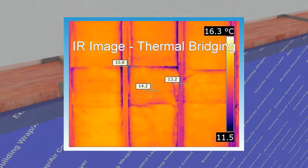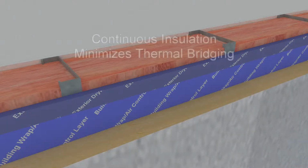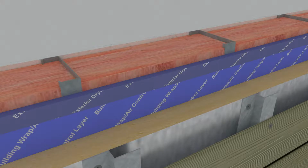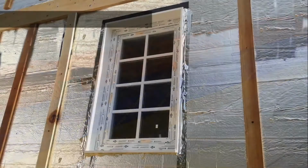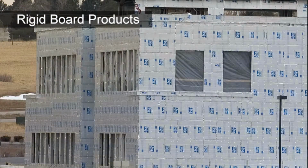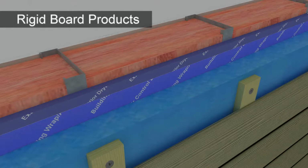To achieve maximum thermal performance, today's advanced wall assemblies include a layer of continuous insulation to mitigate the effects of thermal bridging through framing members. The challenge: to provide a continuous cover of insulation without affecting the wall's ability to dry to the exterior. A common approach to achieving exterior continuous insulation on a wall is to utilize flat, rigid plastic foam insulation board products, both faced and unfaced.